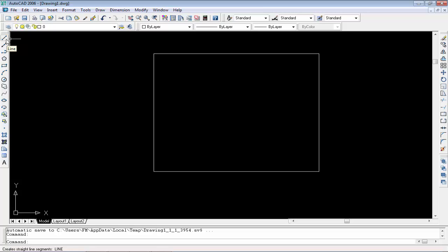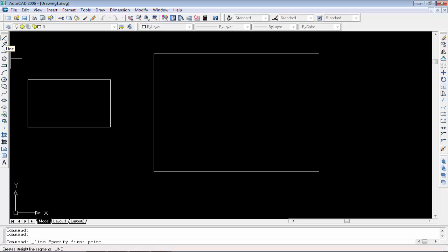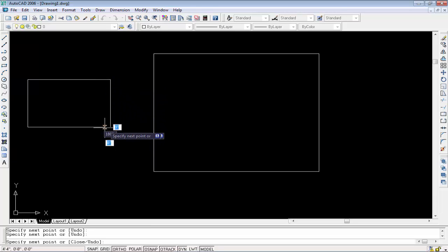If you have got some issues in your drawing, such as duplicate lines or double lines, you will use Polyline. Okay, if you have got some issues in this room or this rectangle, you can't use this line option again, because when you use this line option, it will work the same as I have drawn, so it will not work, it will not extrude completely, and you can't go to the next section, the 3D section.